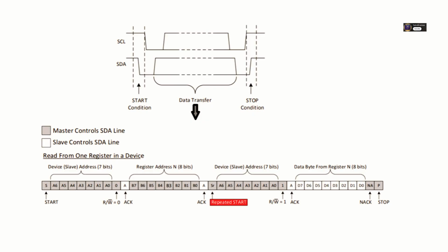It lets the master send the register address, write phase, then immediately send the slave address again with the RW bit flipped to read without ever letting go of the bus. It ensures the whole write address, then read data sequence happens as one uninterrupted transaction. It prevents another master from jumping in mid-operation. Ah, okay. That makes perfect sense. Like saying, hold on, I'm not finished, just changing direction. Essential for those multi-part commands.